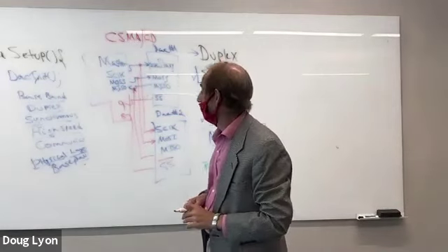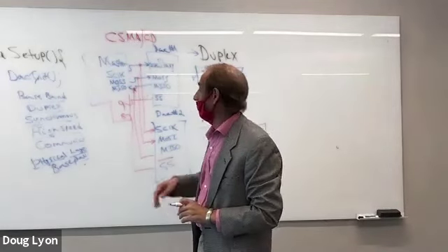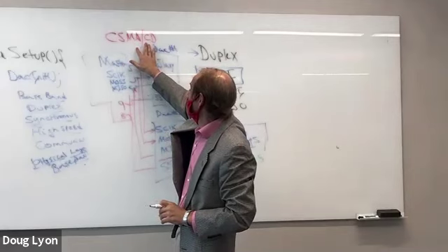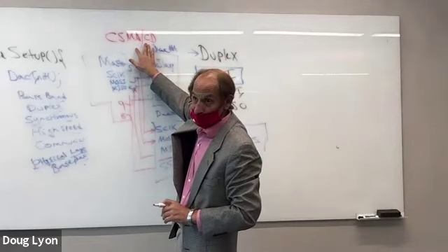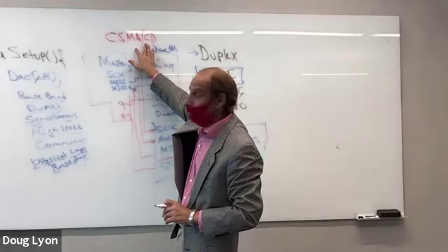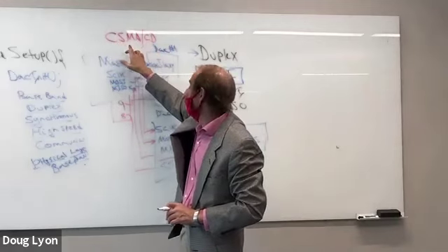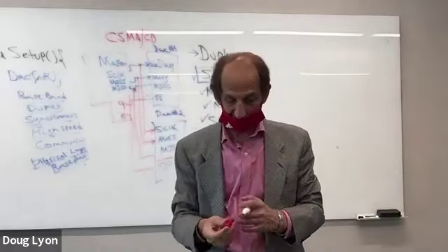Yes, everything can talk kind of at the same time, but what you do is you develop a time division multiplex system, and when two devices try to talk at the same time on the same local area network, the collision is detected because they sense the carrier. But they do permit multiple access using time division.